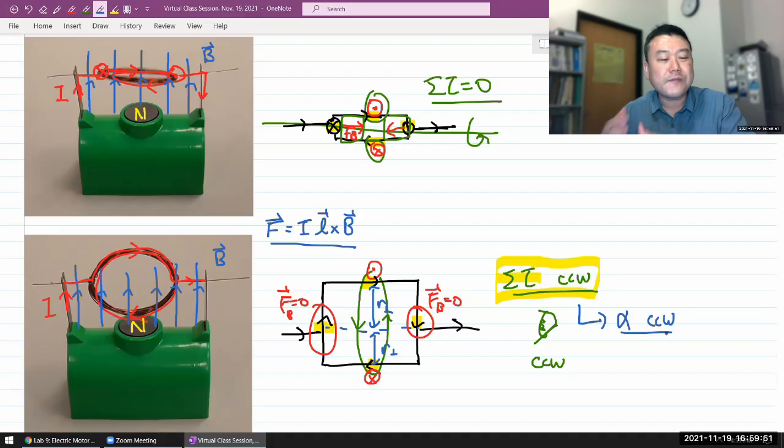And you might say, oh, eventually the friction and whatnot is going to be too much. Okay, then why not the regular motors with friction-minimized bearings and all that? Why don't those spin out of control? And I guess with the more complicated motors, you could imagine that there's some kind of regulator built in. Well, they don't, but what they do have is nature's regulator. There's a secondary effect that will happen as this loop of wire spins.